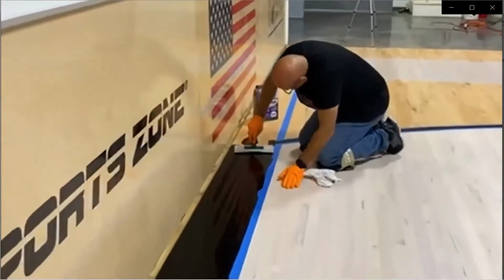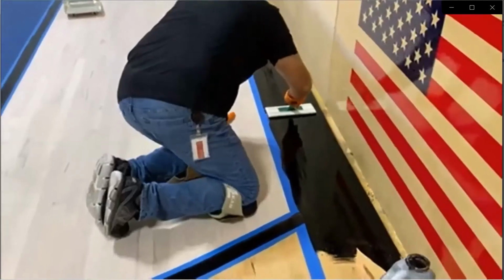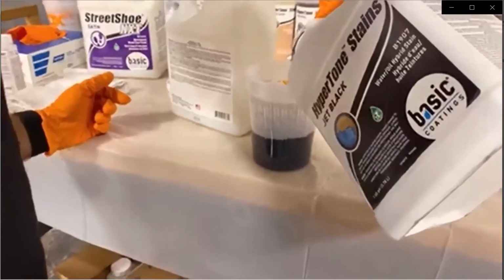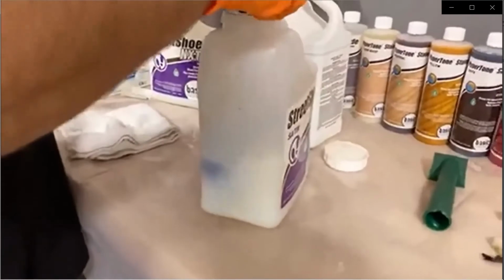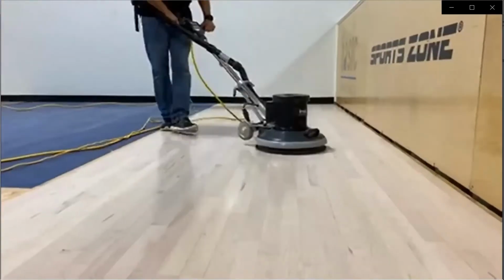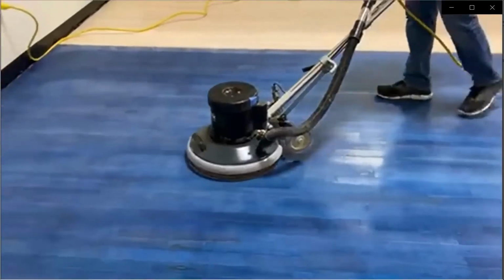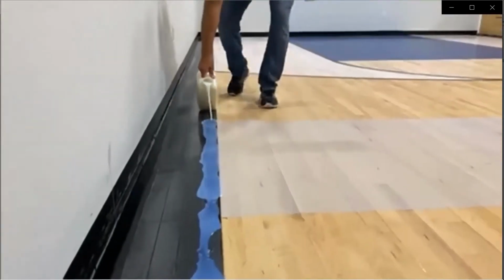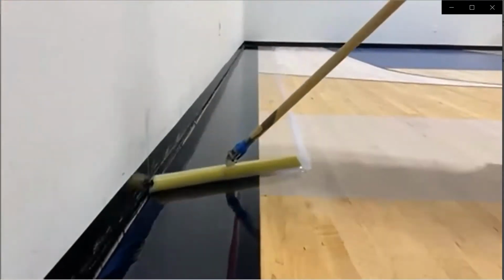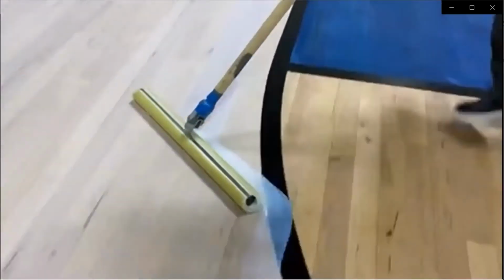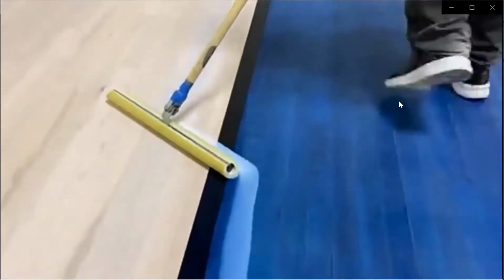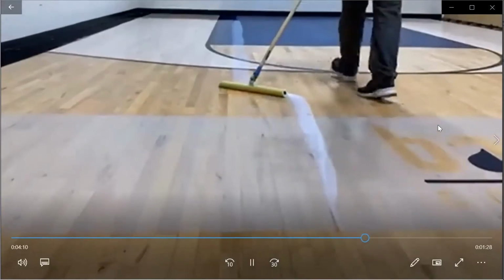This is best accomplished using a professional-grade foam sleeve or paint pad. Apply HyperTone stains mixed with finish in a manner similar to paint. This includes abrading between coats, applying within 24 hours of a previous sealer or finish coat, and allowing adequate dry time before applying another coat on top. Coating procedures will vary based on the desired colors and opaqueness. However, most applications will likely require at least 2 coats.